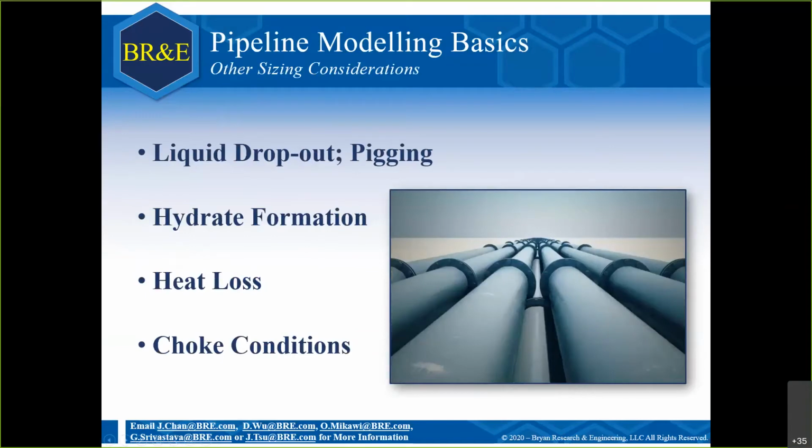But of course, beyond complex multi-phase pressure drop calculations, there are also some important thermodynamic calculations required for other considerations. For example, figuring out the liquid dropout for gas pipelines especially, to ensure you're not forming any solid hydrates that might form across your whole line, and determining if insulation is required or sufficient to deal with heat loss if you're working with a colder environment. Or, of course, figuring out how much feed you can put through your pipeline before the pressure drop starts to get out of hand.